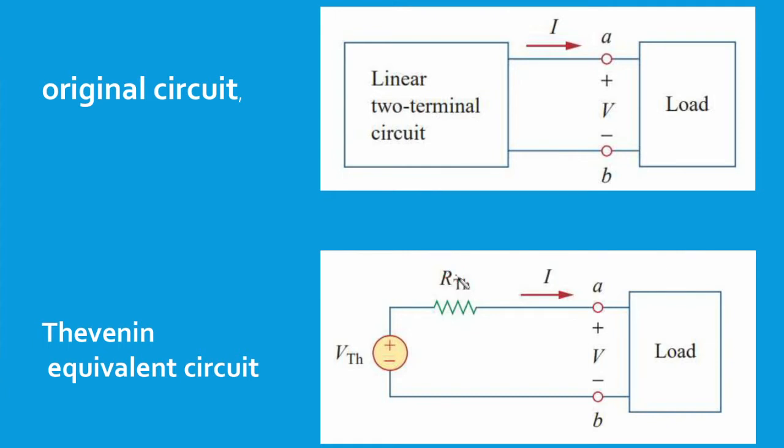Load means you may connect a mobile phone, you may connect a TV, whatever. So load is generally varying. So for a variable load, you need not calculate the voltages and currents flowing through it every time. For that, we will replace the entire circuit by a voltage source in series with R Thevenin. Okay, that is a very important concept.